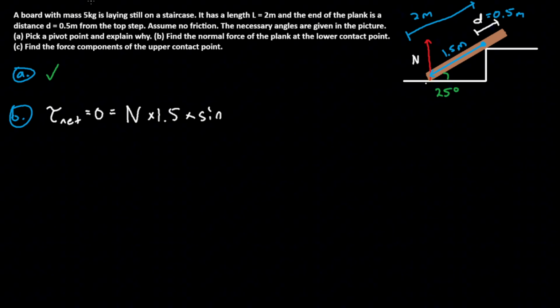But how do you find the angle between them? Remember, we need to put the vectors tail to tail. If I put the distance vector tail to tail with the force vector, we can find that. We know this distance vector makes a 25-degree angle with the horizontal. So if you shift this tail to tail, it should also make a 25-degree angle with the horizontal on the top end. And we know that the normal vector makes a 90-degree angle with the floor. So we just need to add 25 plus 90, and 25 plus 90 is equal to 115.